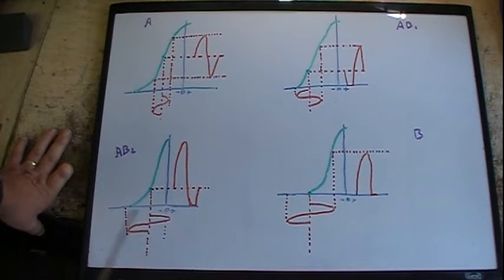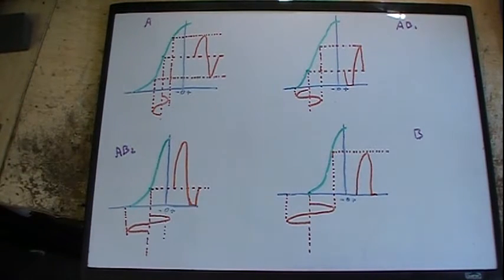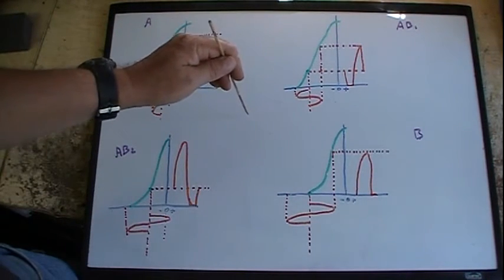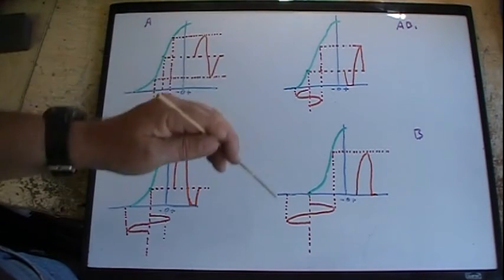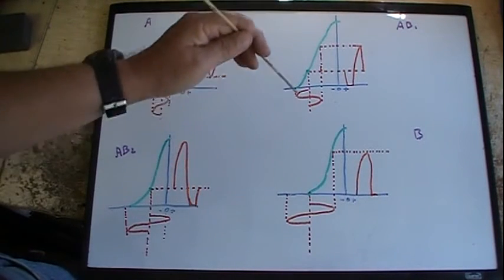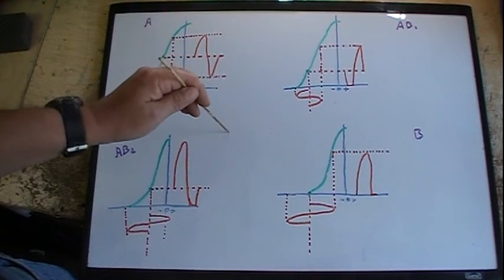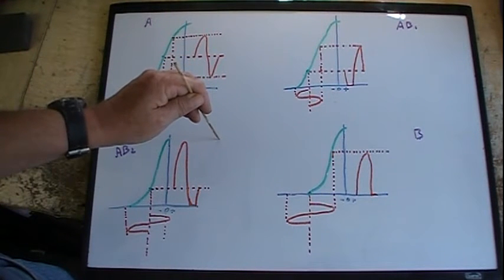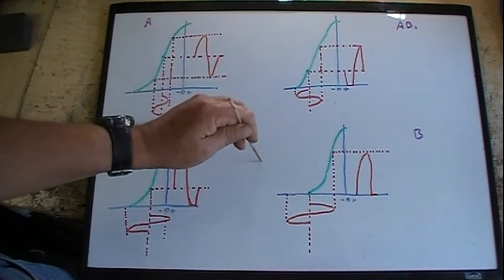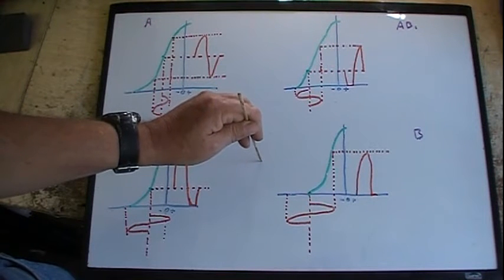At some point I may draw up how you can do that in a future video. Or you can pull it off the cathode by putting a voltage divider in there, and you can pull some current out from there and feed it. If you pull it off the cathode, you don't have any gain from that first audio, but you can always put a tube before it to give you some more gain. Amplify it, run it through that, a cathode follower is what they call them.